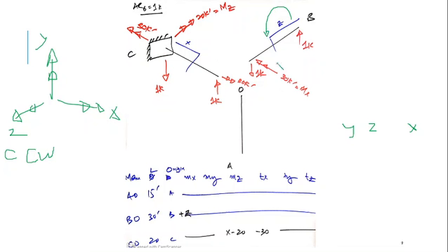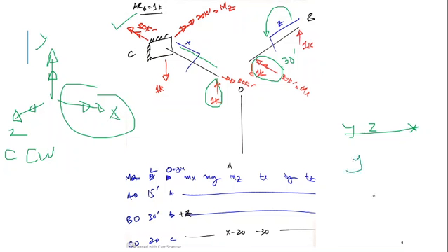It would be balanced with a clockwise moment in X direction, because this is anti-clockwise. Because the distance is 30 feet, it is 1 into 30, so this 30 kip-foot would be balanced here, and it would be taken here, 30 kip-foot, as it is. Okay, this load is in Y direction, this member is in X direction, so there should be a moment in Z direction.